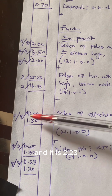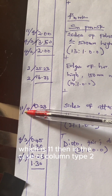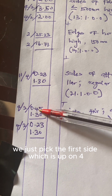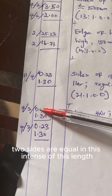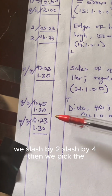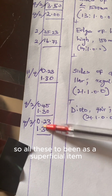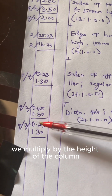It is 0.23, so we slash by 4 and slash by the number of columns, which is 11. Then in the case of column type 2, we just pick the first side, which is 0.45, which two sides are equal in terms of this length. We slash by 2, slash by 4. Then we pick the other side, which is 0.23, slash again by 2 and by 4. So all these, to be in as a superficial item, we multiply by the height of the column.